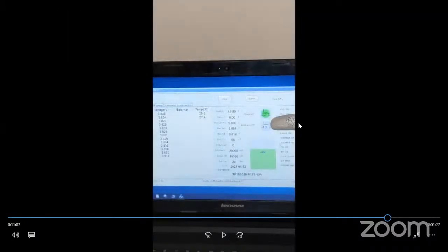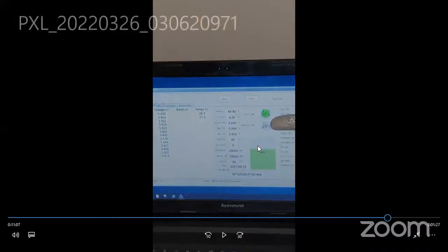And again, the question is, how long will it be in cutoff state? That's what I mentioned, there was a parameter setting called delay seconds. Based on the amount of delay seconds you give, it will stay in cutoff state. After the delay seconds, it will reactivate and recheck. If all is fine, it will continue. Otherwise, it will again deactivate. These delay seconds are all based on the safety factor. Based on that, these values are set.